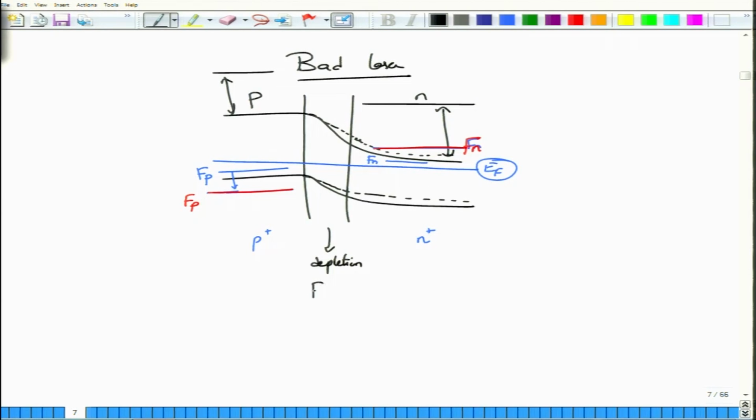Reducing the barrier height means the electrons here can reasonably easily move to the p side region, and they diffuse while they do that. The holes present here will also move into the other region, and when they are there, they will recombine to emit light and create a laser.